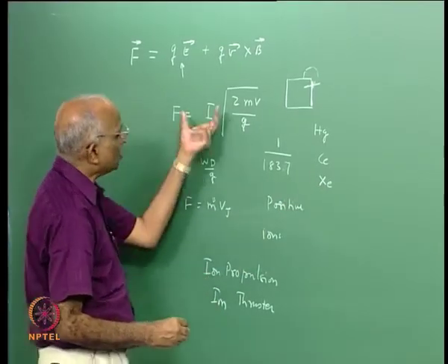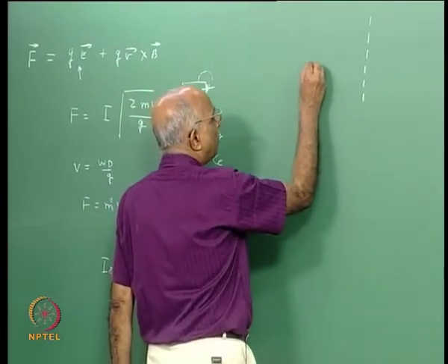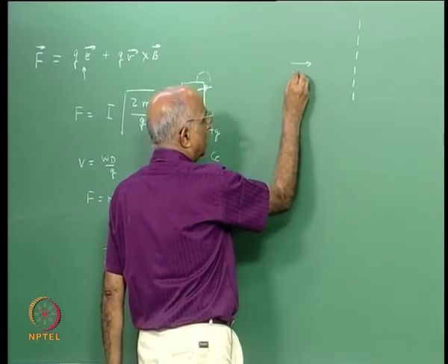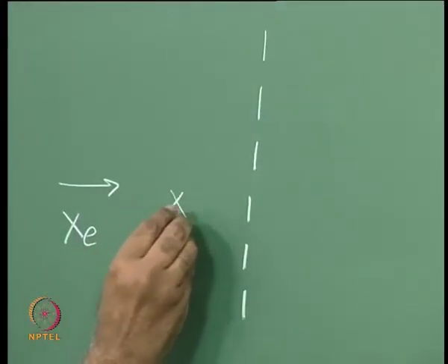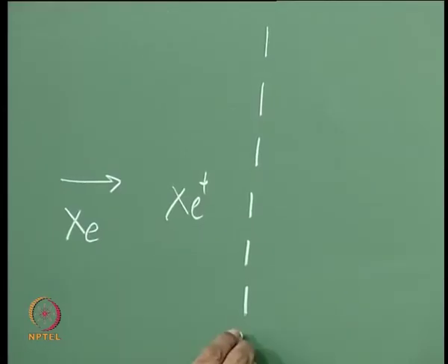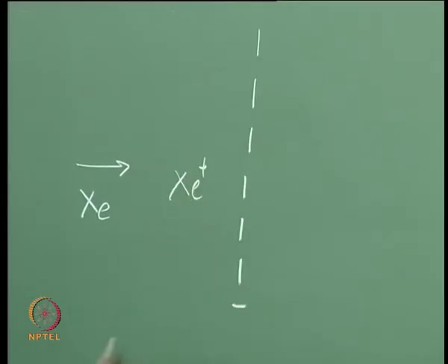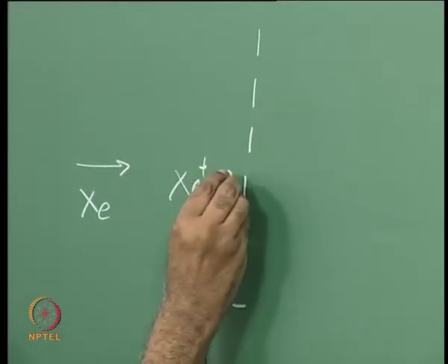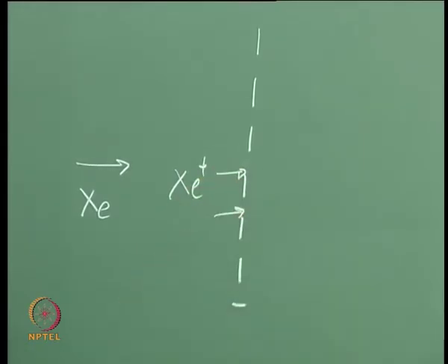Therefore how will the construction of an electrostatic rocket look? Well, I need to pump in this particular xenon gas, I need to generate positive ions of xenon, and then maybe I put something like a negative grid over here, a screen which is negative, such that it will attract the positive ions towards it.